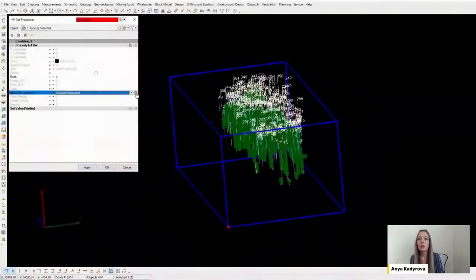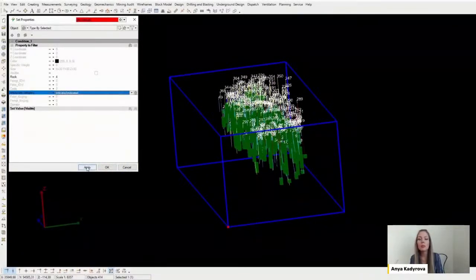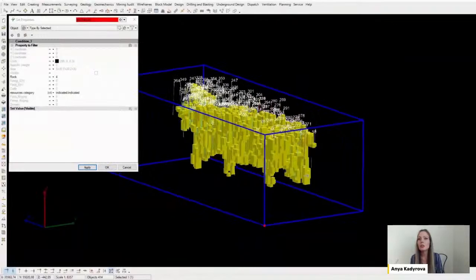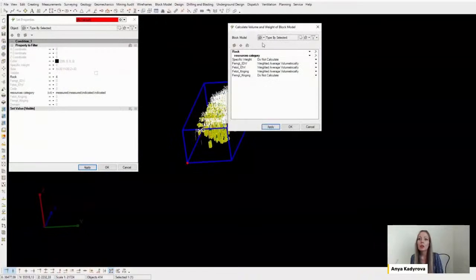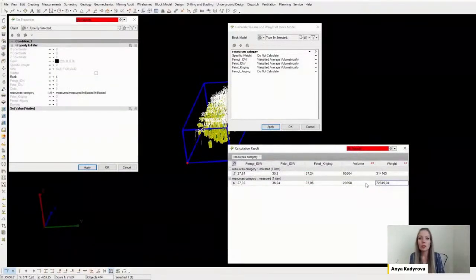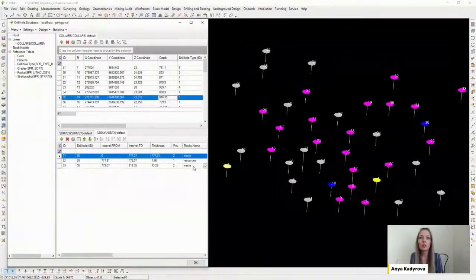And when you create a block model in K-Mine, you can conduct an operational feasibility study at any stage of the deposit development, determine the optimal contour of the boundaries of mining operations, justify the most effective options for mining deposits, and so on. You can also proceed with effective planning and design of mining operations and prepare the necessary package of graphic documentation and so on. The system also implements several methods for volume calculation, among them the method of nearest area, the Bolderev polygonal method, which is also called polygons of Thiessen.